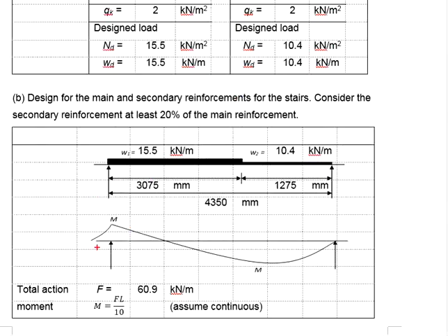First, you may observe from the bending moment diagram, especially the regions at the support here. You will see negative moment at the support, and you know that the existence of negative moment will require top reinforcement near the support. Now, if you wish to know where the anchorage should end, most likely you can consider that the anchorage should end at the zero moment. This is one of the possible considerations when you decide the layout of the top reinforcement.